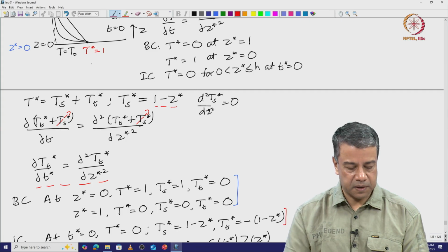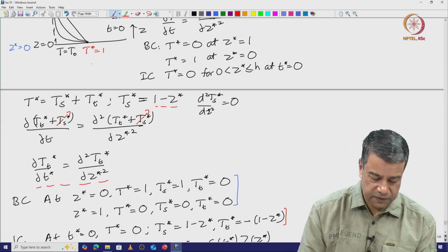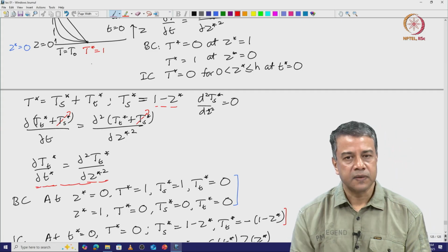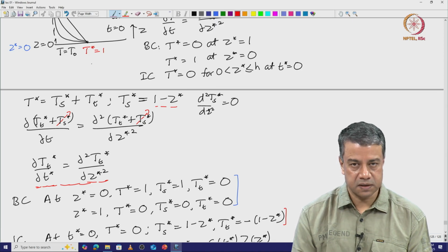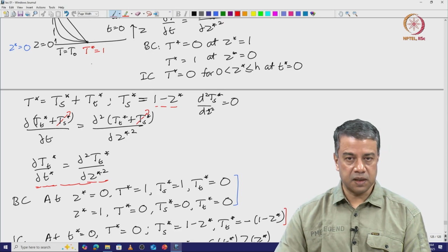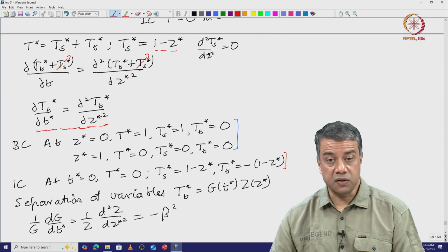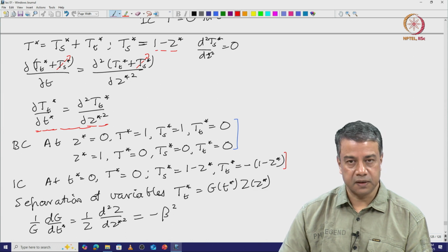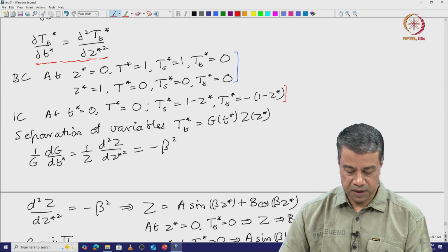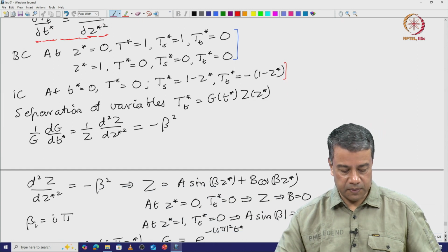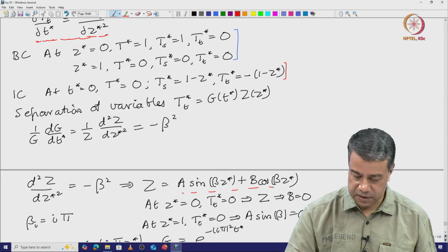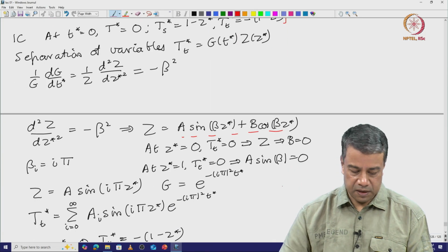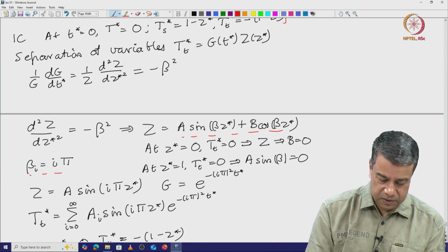The transient part, the equation for the transient part, this is important. It contains homogeneous boundary conditions in the spatial coordinates. The transient part of the temperature is 0 at both boundaries, it is non-zero at initial time. Because it is 0 at both boundaries, we were able to express this as the sum of sine and cosine functions, and these are what are called eigenvalues.